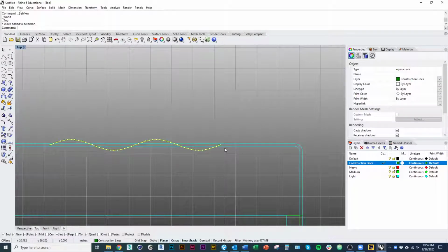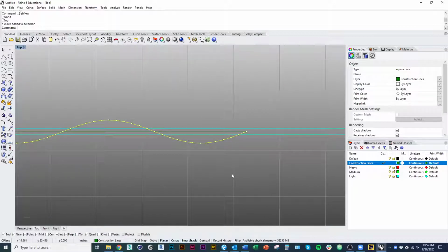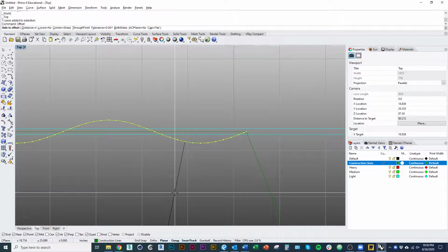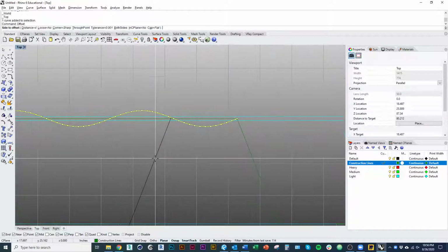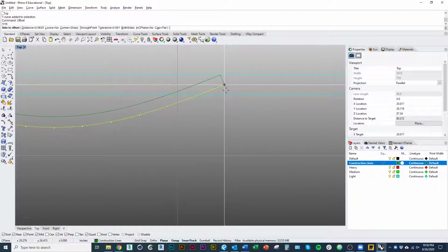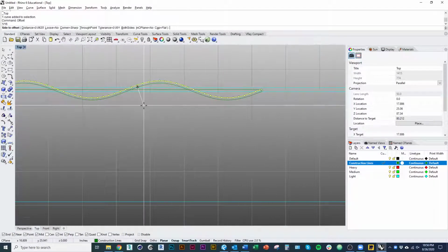So now I'm going to take this line and offset it from the center to create the top and bottom line. So I'll offset. And this time I can do another little trick. First of all, I'm going to offset it by 1/16 of an inch, because that'll make sure it's the right thickness for my handle, which is a total of an inch.